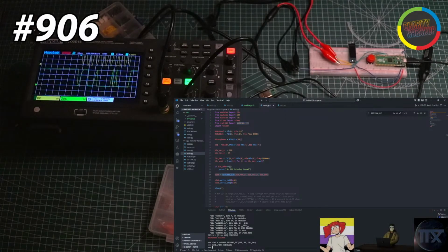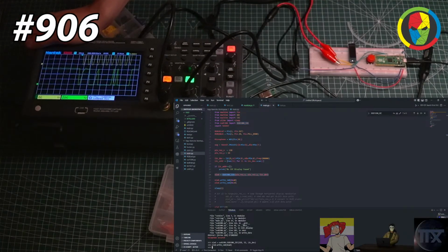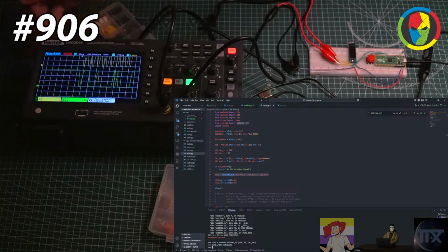If I had this when I was dealing with UART, then I could just plug this bad boy directly onto the pins of a Raspberry Pi Zero and see what it was doing. What's more, when I connected my Raspberry Pi Zero to the Pico and scanned on I2C, the scan took a really, really long time. And right here, I could actually figure out what was happening during that time. I'm guessing the code was running too many times, because I've only done that when I've put the I2C scan within a loop.